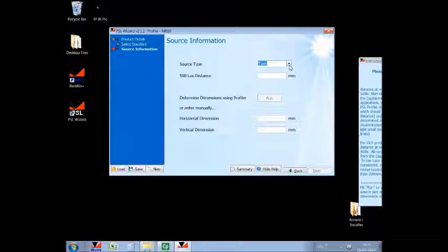We will take this MR16 as a non-GLS source in this case. The distinction between GLS and non-GLS has always been one which has led to much dispute. Here we will have more information in performing a non-GLS evaluation, since I can tell you presently that GLS sources in all cases will be exempt for all hazards. So non-GLS. Now we will use the profiler again to determine the size of the source and the location of the source. This is the procedure we looked at in a previous video.